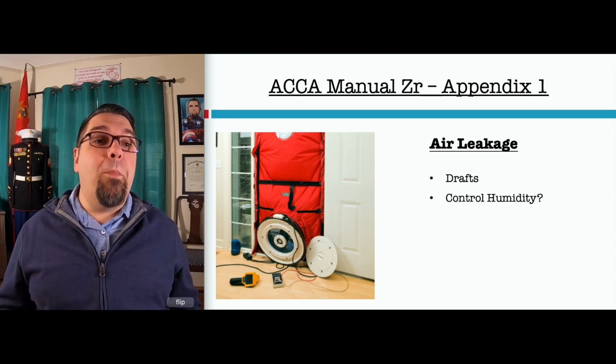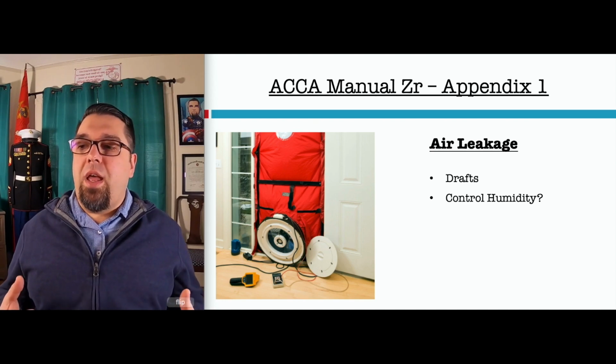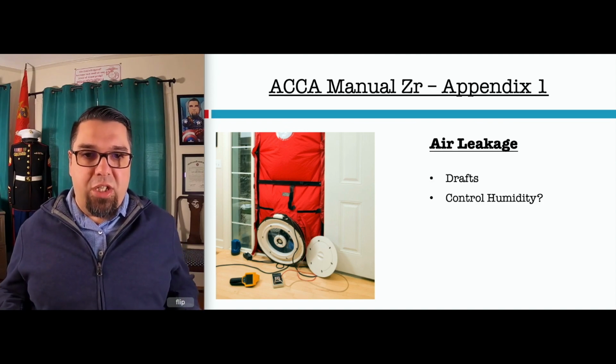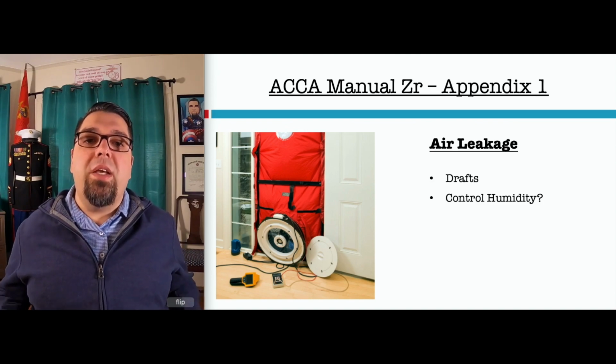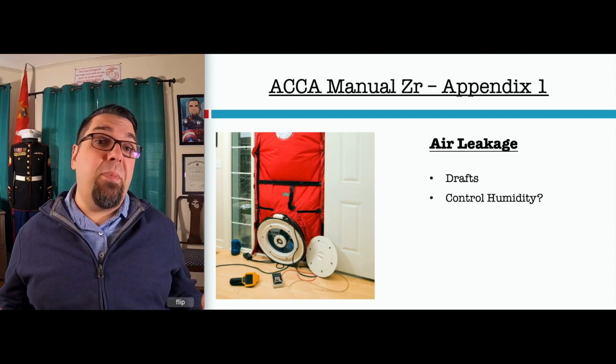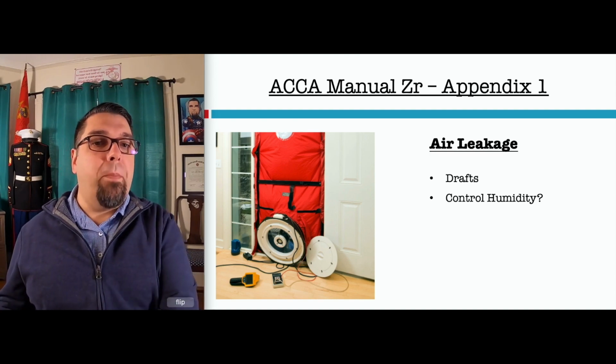Also, when you have a lot of air leakage in the summertime, you're going to have a big humidity problem, particularly coming up from basements in the Northeast, right? There's a lot of crawl spaces and unfinished basements, and if it's not air sealed with insulation and a slab, you're going to get humidity and temperature differences across those floors, and you're going to add a lot, especially if you have a lot of duct leakage in a basement, because you're going to have negative pressure pulling in all of that moisture.